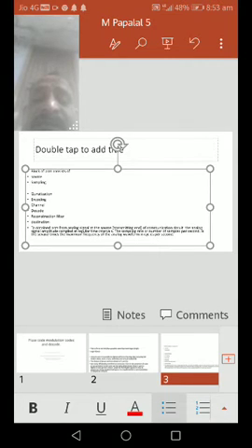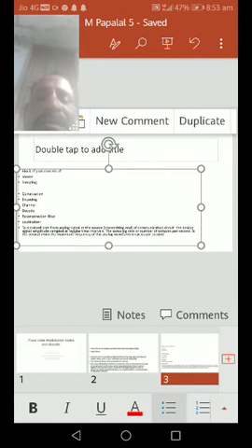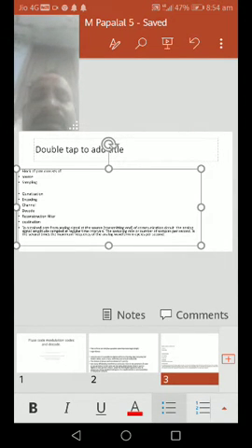To obtain PCM from an analog signal at the source end of the communication circuit, the analog signal's amplitude is sampled at regular time intervals. All the sampled voltages are at regular time intervals, to convert to digital according to the instantaneous voltage or current. Sampling rate is the number of samples per second, how many samples of the data are transmitted per second, and it is several times the maximum frequency of the analog waveform in cycles per second.